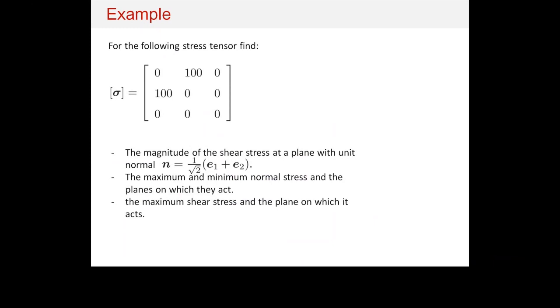One example. I'm proposing a very simple example in this case because I really want you to see things. Now, what I'm doing in this case, I'm projecting the entire stress into the shear direction. This is not quite a realistic case, but if you want to think about this in terms of the uniaxial test, for example, if you have a bar and you have one force, or probably a distributed force, on this end here, and you want to project this into only shear, think about these forces trying to cut across this line here. So on the surface of this line, you will have the entire stress acting as a shear force.